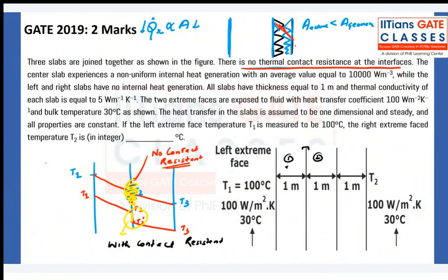Okay, now what is the second reason? In these voids, air and gases can get filled. Now because of these gases, we already know the conductivity of gas is much less than the conductivity of solid. If two solid bodies are connected together, it will have much higher conduction resistances.